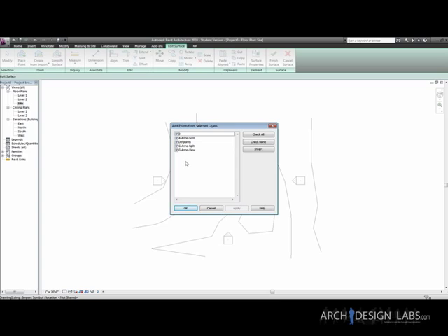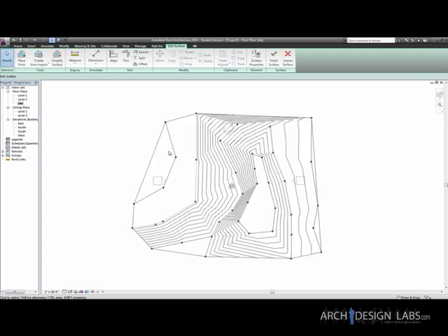It's a simple DWG, so it's not really going to hurt us too much, but you really need to know what layers the contour lines are actually on, and just select those layers instead of all of these. Pretty sure they're probably all on 0, so let me just go ahead and select 0 and say OK. And it'll create that surface for you.